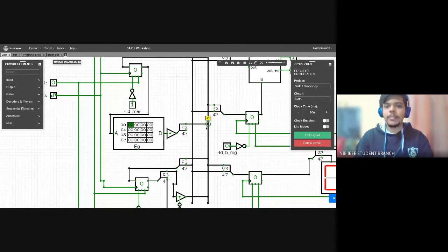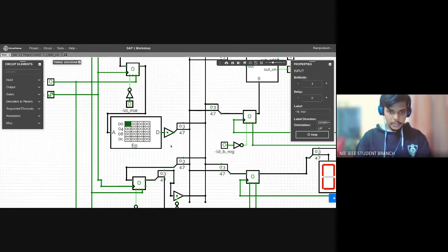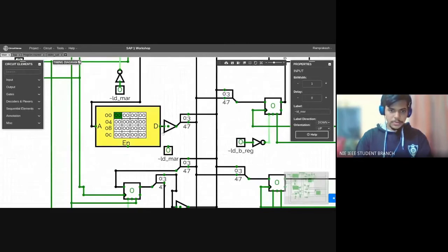Right, so the lower nibble goes to the lower bus, and then this goes here. So what's left is this enable signal. So I'll take this. Guessing that's also an active low. So we'll grab this inverter, put it here.